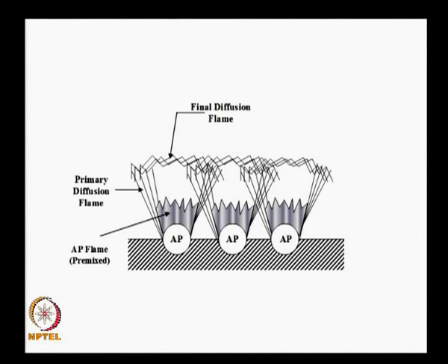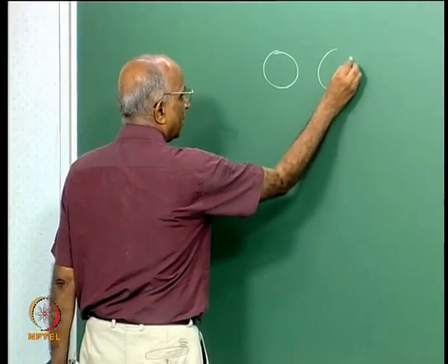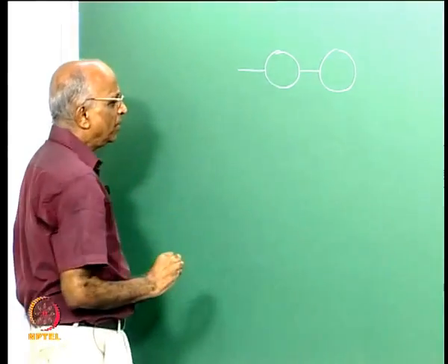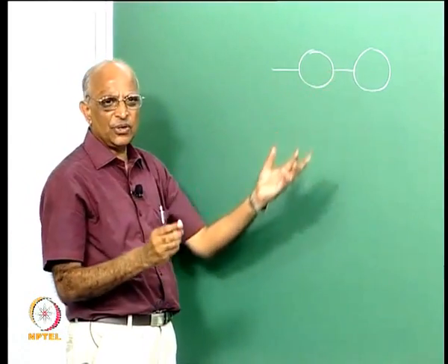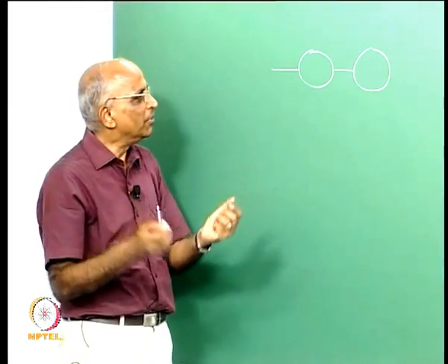composite propellant, and a composite propellant is distinctly different from a double base propellant. What is the distinction? Let us put it on the board. We said AP in the form of crystals, and this AP is contained in the polybutadiene. We could also have aluminum, just like we saw in the sparkler. When there is metal, it is much hotter, and that is why aluminum is put.